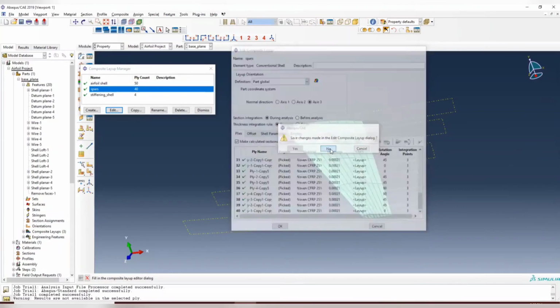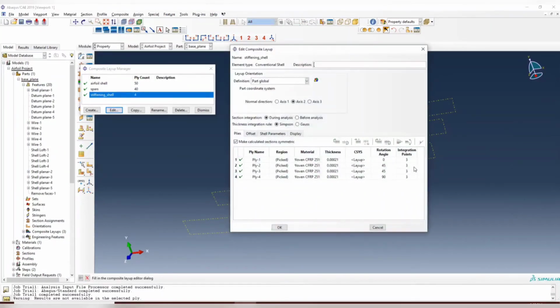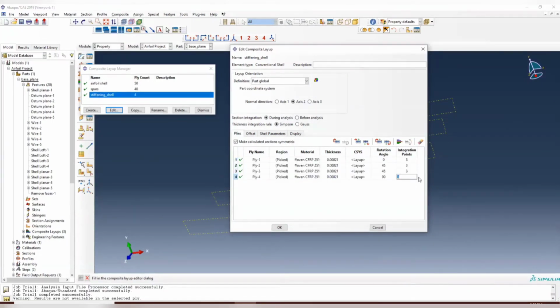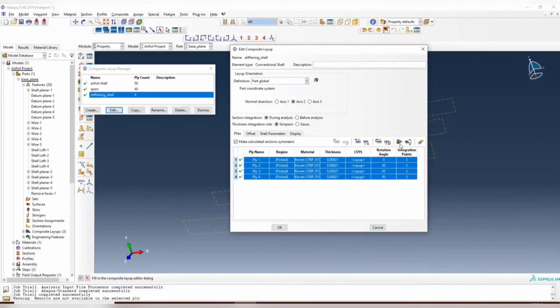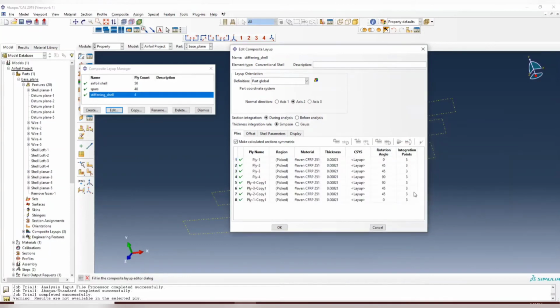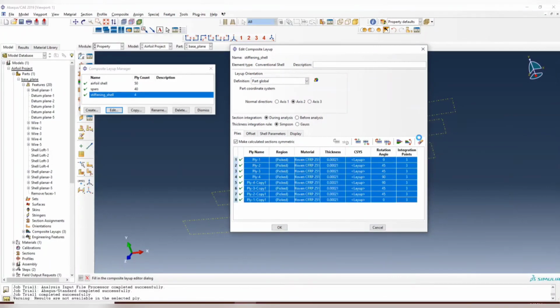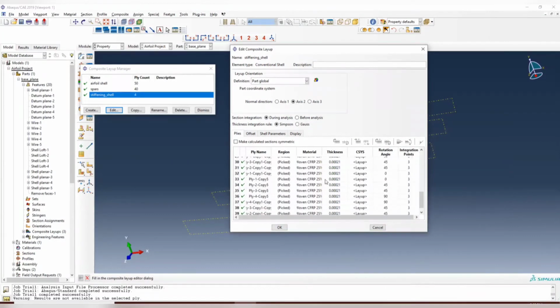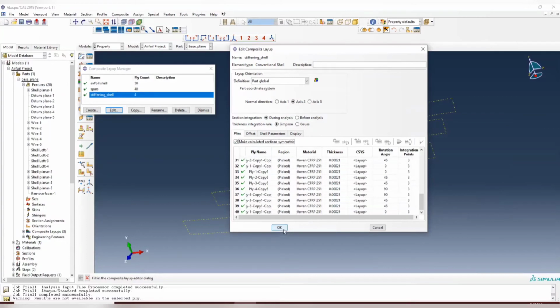And same thing here. Do symmetric first, and then we can uncheck the symmetric first. Sometimes it will run; you will need some time if you check this box. But n plies, n copies 4, and then it should end at 40, and then check the symmetric.